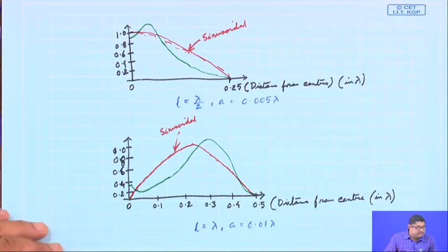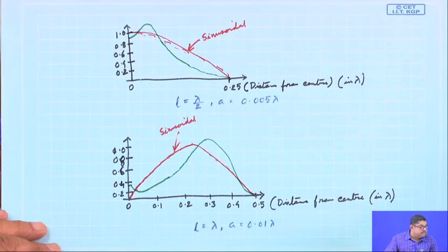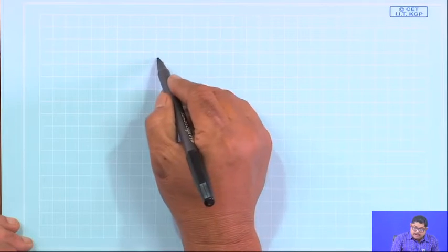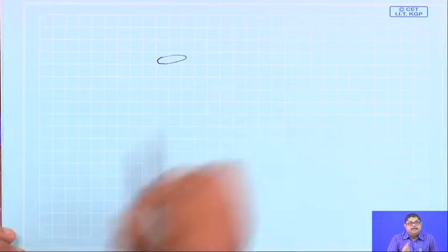Today's topic is numerical evaluation of the dipole current. So, let us say that we have a dipole. In the earlier discussions we always neglected the finite radius of the dipole, but if I want to make a dipole, it will be a cylinder. Any practical cylinder will have a finite radius. I can keep it small, but that means on the surface there will be currents. If the dipole is made from perfectly conducting or any practical elements, there will be currents in the circumference, so it is not always that the current goes through the center.